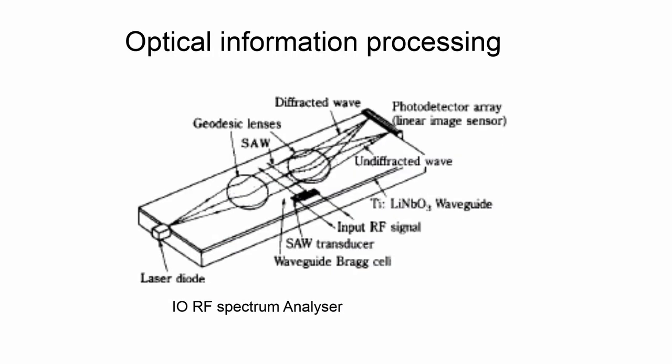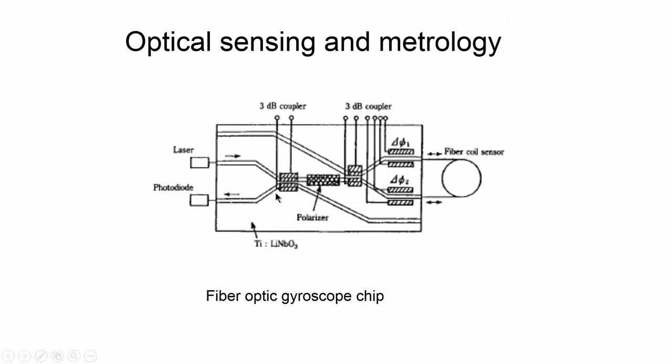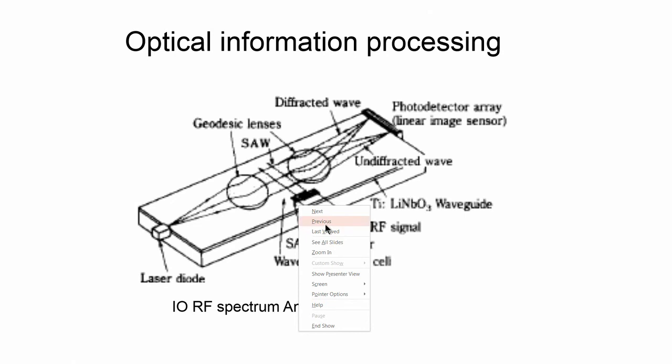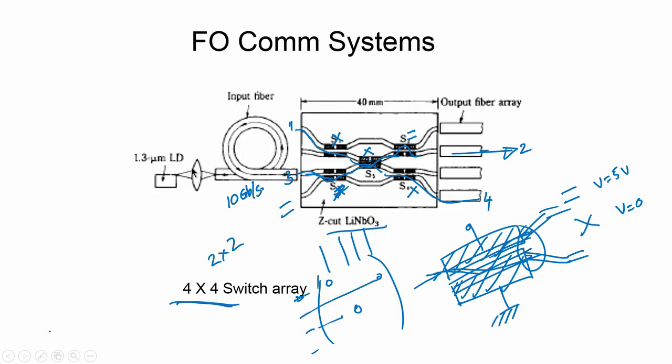and they are modulated, the signals are modulated at 10 Gbps. Typically laser diode transmitters are used, and at the output, if you want to detect the signal directly, you can put photodetectors. Of course, many times, up to 10 Gbps, you can also use direct modulation of laser diodes.